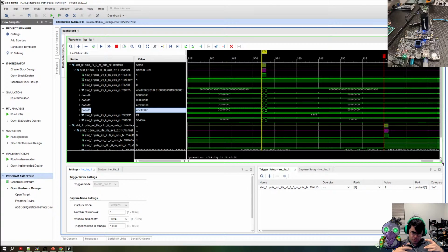We split it up between different systems. Because our bandwidth is not being able to parse everything every cycle. We want to speed up the MicroBlazes. We want to maybe have a MicroBlaze for each different interface, and then have a logging system that just captures the data statistically on the other side.